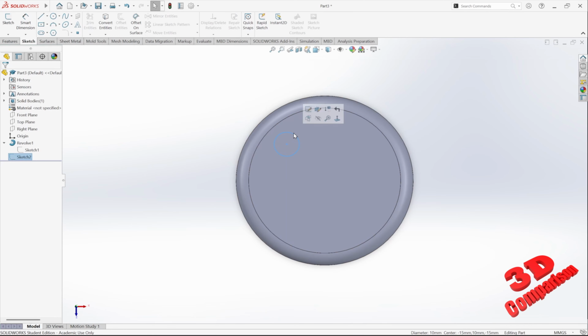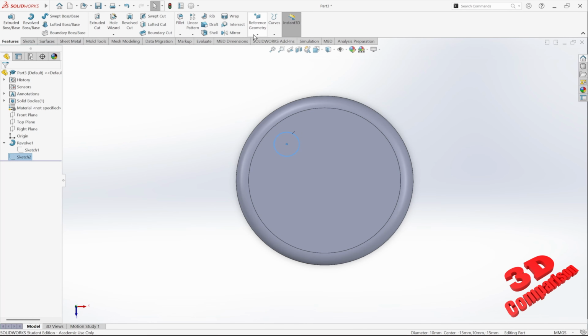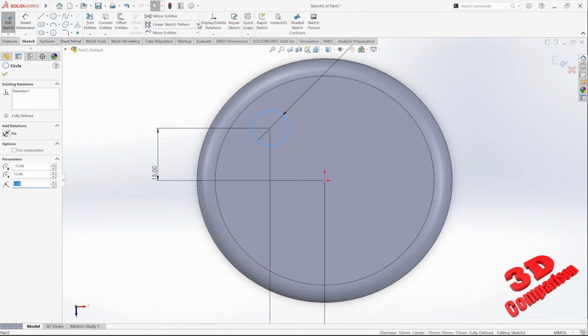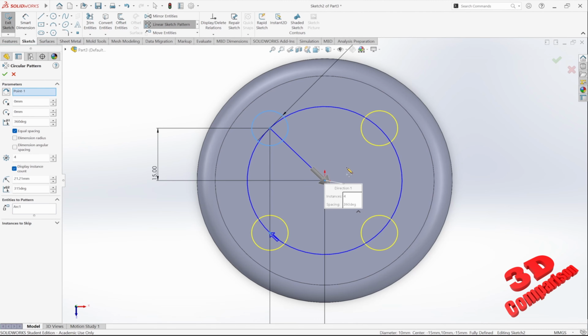And I want to do a circular pattern for this. I'm going to go within feature. I can also do it directly within sketch, so I can remain within sketch, have that selected, define it over here. SolidWorks will automatically move that point to the middle. If you didn't use that as the origin, you can change it over here as well.